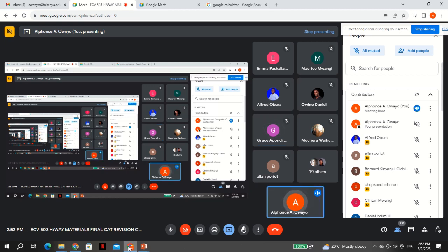You can redesign, yes, you are allowed, because the asphalt content is not the controlling factor. The factor is whether in that mix the stability is okay, the void ratio and so on. Normally the standards give an asphalt content of, I think, at least between 3 to 5, something like this. So what guides you within the range of the asphalt content that you have chosen? Check whether the requirements of the void ratio, the stability, and so on have been met according to the restrictions. So what you can do in that case is redesign, readjust the values a little bit.